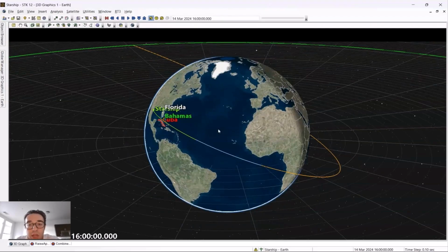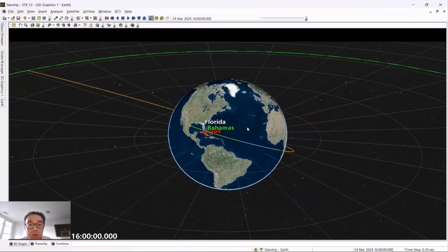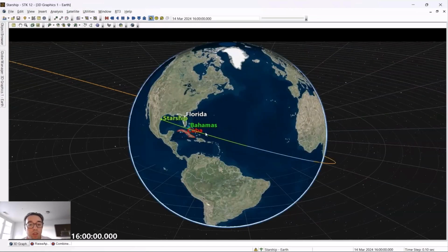And we managed to show that Analyzer can allow us to find an optimum value for our design variable. In this case, the downrange distance was 5,000 kilometers, and our azimuth was 92.3125 degrees. And lastly, we saw that we were able to input errors into our runs and define the standard deviation for these errors, or the type of distribution. And this is a really important part of launch safety.